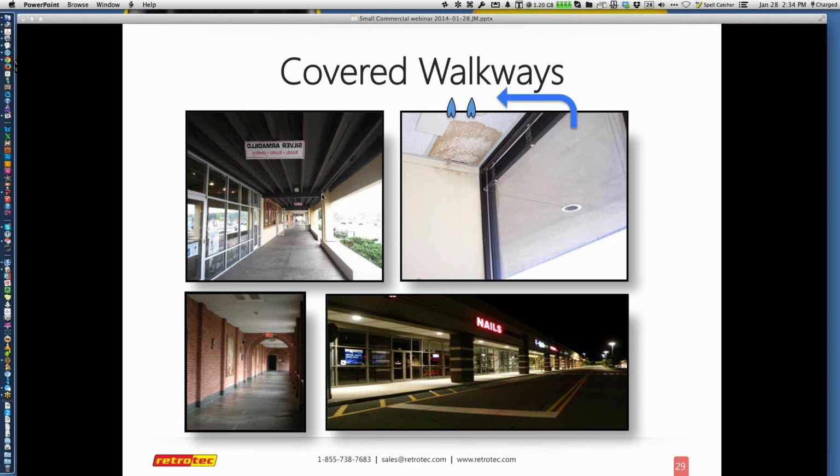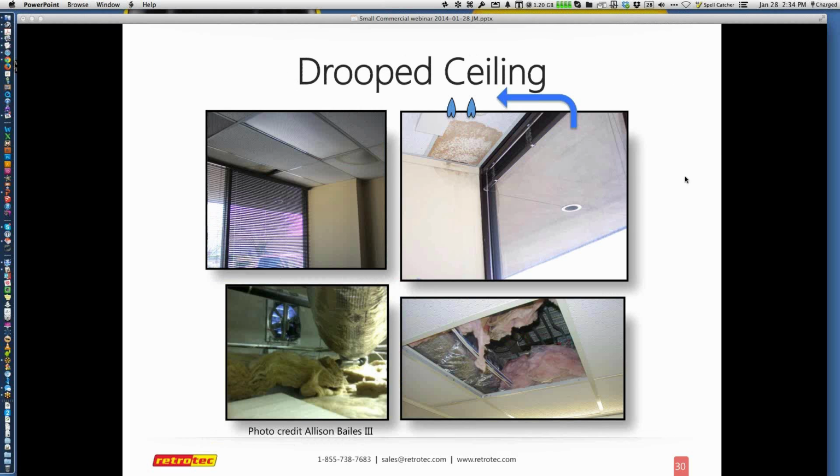So this is one of the most common defects that I felt was out there when we talked about these kinds of structures: the drop ceiling, and it's not a misspelled title there. Many of them become droop ceilings, or they just have a lot of issues above them, or are poorly installed, poorly maintained. Many of them have insulation up there and may or may not be a free vent or an open plenum concept. Many of them are also exposed to cold surfaces like the back of the wall or joining walls, and that's also causing them issues.